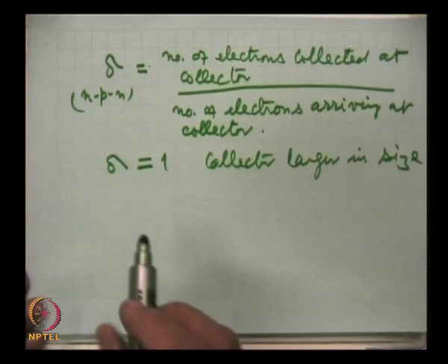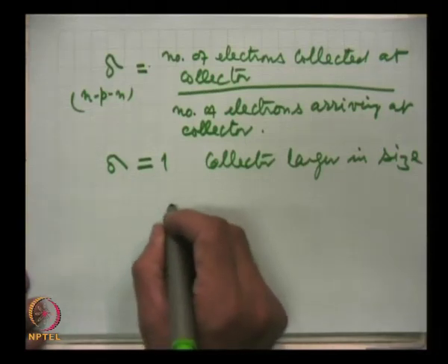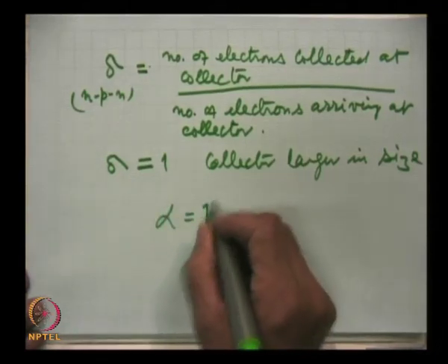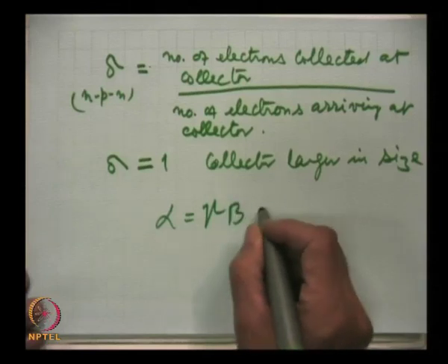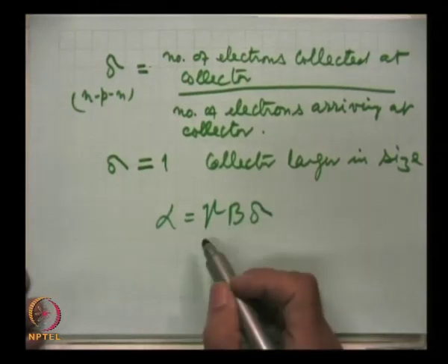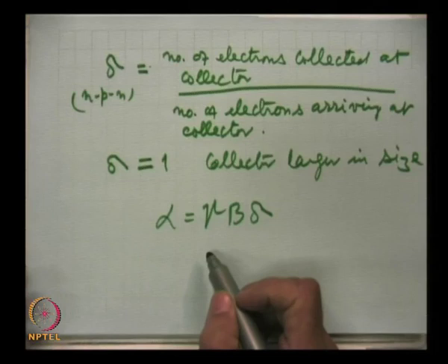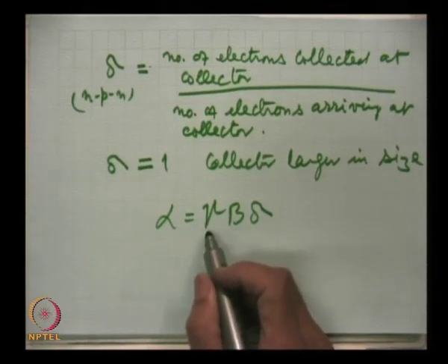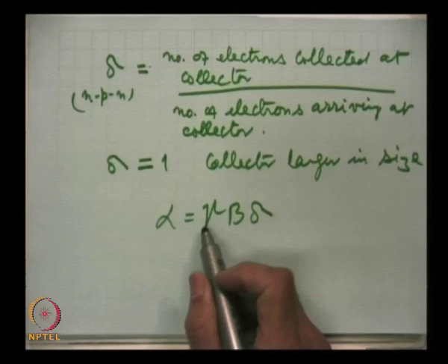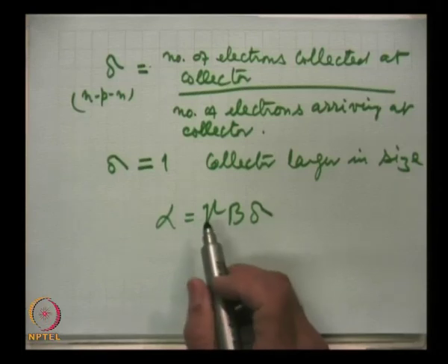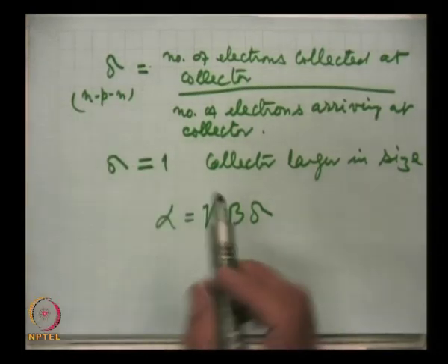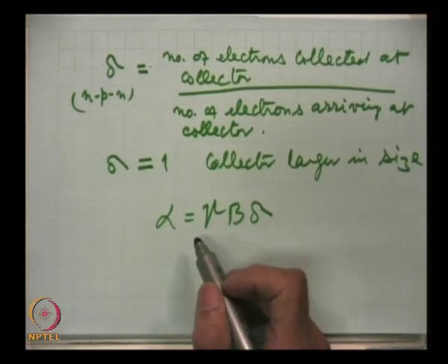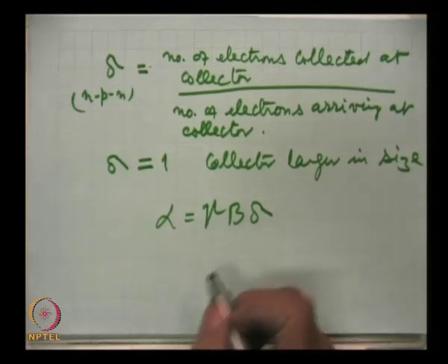So, in summary, in an efficient transistor, the alpha is composed of 3 components. This emitter efficiency can be obtained closer to 1 by making the hole diffusion in an NPN transistor less, that means by doping the base lightly.